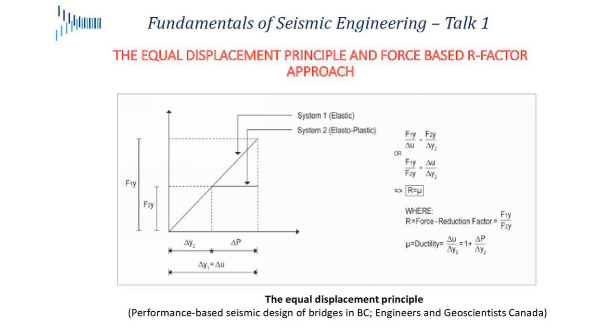What I want to say to you is start thinking about earthquakes, the seismic phenomenon, primarily as a displacement demand on your structure. Forces are very important, and as structural engineers, we are trained to think in terms of forces. What I'm going to ask you to do is keep that thinking in your mind, but put it aside for a little bit and start thinking of an earthquake as a displacement, something that the earthquake is going to do to your structure.